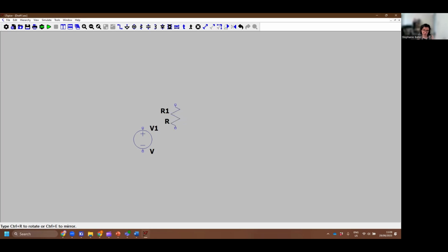And if you needed to rotate components, you can also press Control R to do so. In this case, we don't. They can just both be vertical stacked like that. And then we want to connect them together. So to do that, you'd want to use the wire tool, which is available here, or it's just W on your keyboard, and it'll give you little guidelines to help you line everything up as you go around. And that wire tool will stay on until you're done with it.